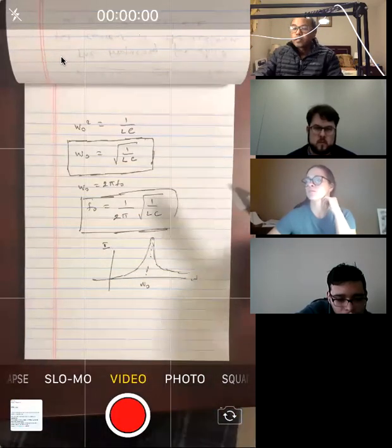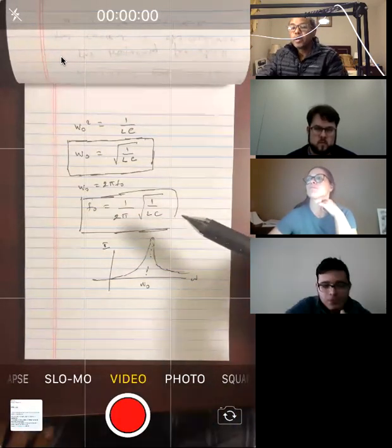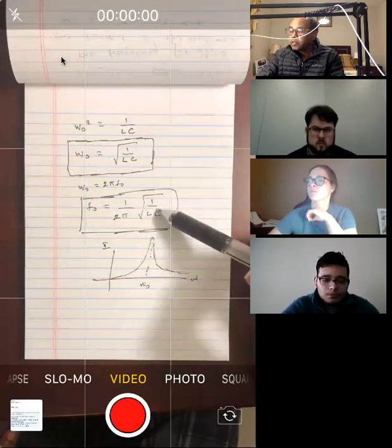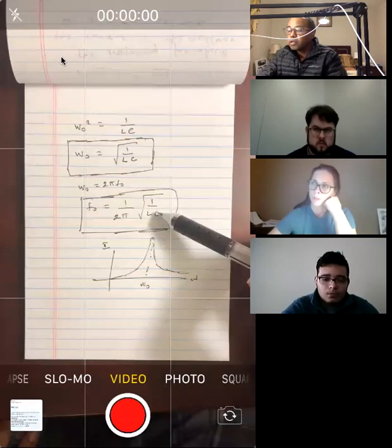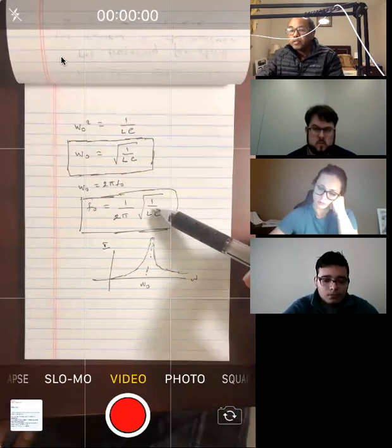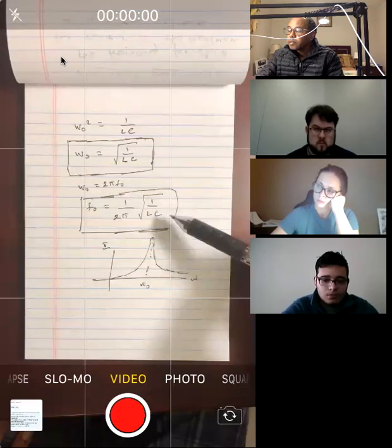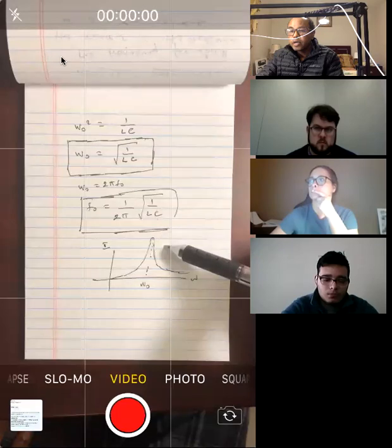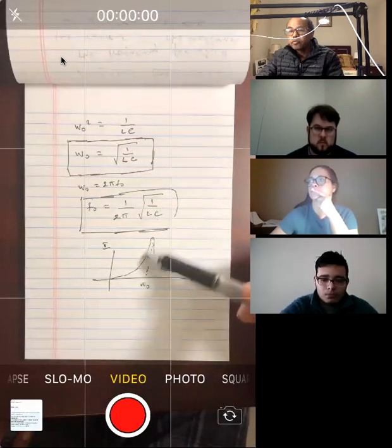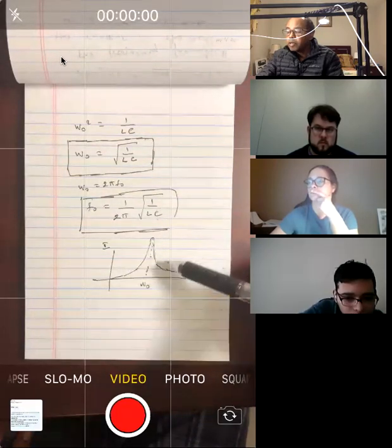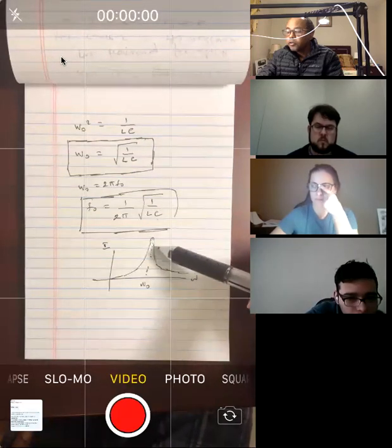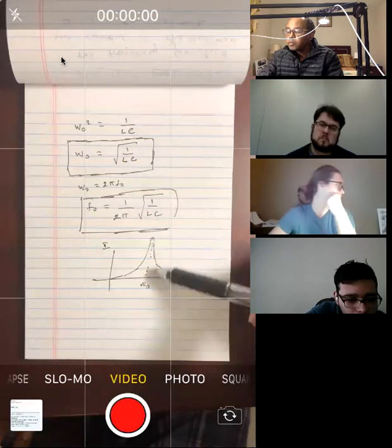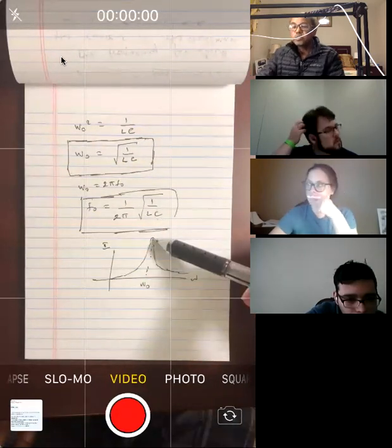Now, if you got a bunch of frequencies coming to your radio, when you dial your radio, you're basically dialing this C. They have a variable capacitor over here. You dial this one to get this frequency over here, okay? So what happens if you've got a bunch of frequencies coming, but for all those frequencies, they're cut off? They don't get any current. You get the maximum current for that frequency. So your radio picks only this frequency. The antenna is going to pick only this frequency because it is for this frequency that current is the maximum, okay?